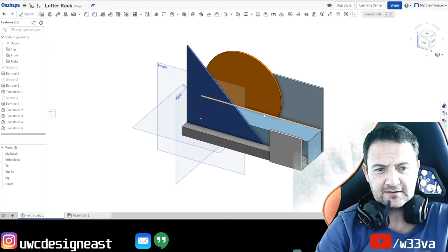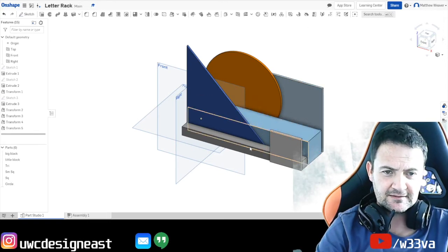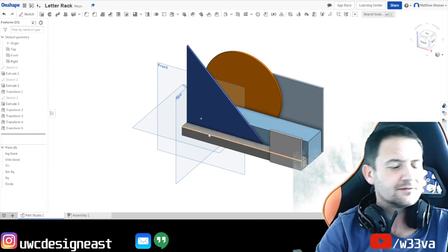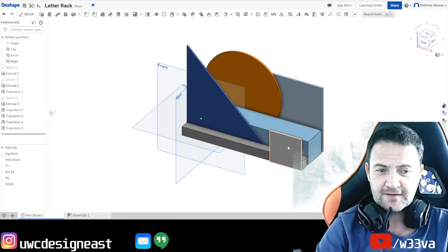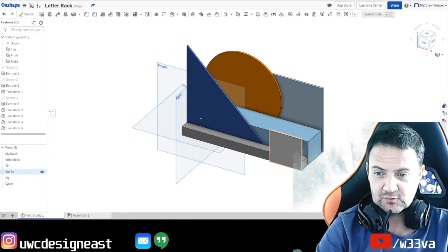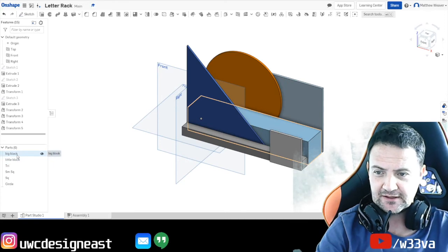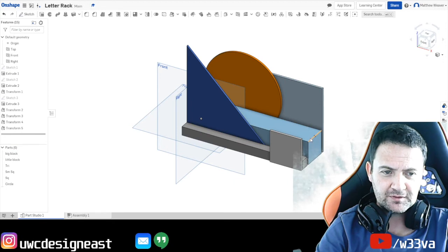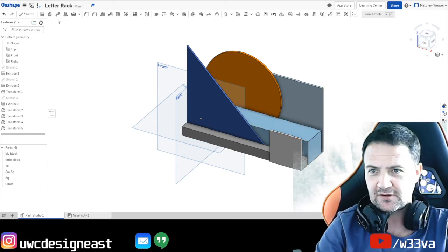Now what I would like is I would like my phone to go up here, and I would like a pencil or something to go in here. So I'm going to show you how to now make a groove and make a hole. Now they're all separate parts, remember, nothing should be joined. So the first thing is, let's show you how to do the groove. Well, we're going to select the big block so you can see it. What I want to do is I'm going to make a circle here, half a circle there, semicircle, and push it forward halfway, around halfway.